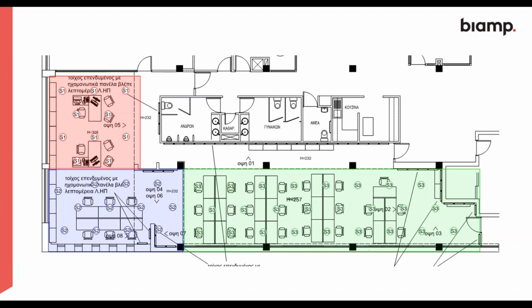What are the minimum and maximum heights recommended for sound masking? If it's anything lower than 2.2 meters, then we really do need to consider putting the emitters closer and also using the active emitter. Much lower than 2.2 meters is not going to be overly effective, and up to about 6 meters maximum.